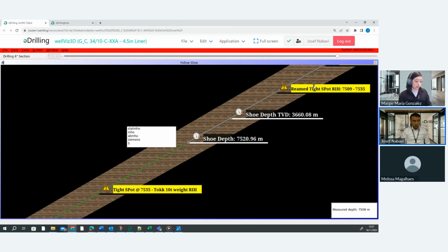And then when it comes to the advisory part, how we can look ahead of the bit. You are taking the current condition of the well, with the amount of cuttings that you now have in the well, how your hole cleaning is right now, flow rate, RPM, and ROP, and based on that you are projecting, running a lot of simulations. What is my best option to drill the next stand? That is how it is advising you the future values.